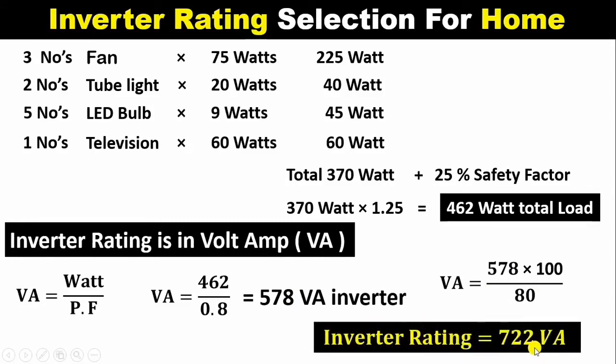However, you might not necessarily find the exact rating of 722 volt ampere in the market, but of course we're going to be taking the range of about 700 to 1000 VA, which would actually do very fine for this inverter size.